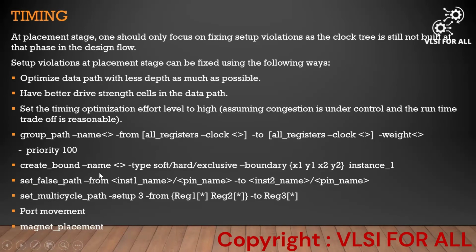And the next one is timing. After fixing that congestion, the other issue we are seeing in the placement stage is timing, particularly setup. Here we are focused only on setup because the clock is ideal.